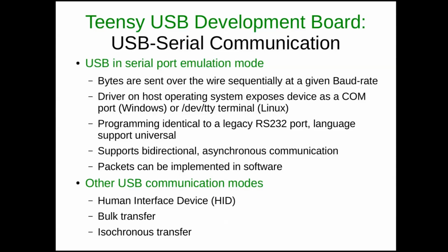We're going to be using the USB bus to communicate between our PC and our microcontroller. But it's important to talk a little bit about the different communication modes that USB uses. The mode that we're going to be using is called serial port emulation mode. This mode is an emulation of old school serial ports like RS-232 or RS-485. Those communication mediums are electrically different. They use different voltages, they communicate over different lengths of wire. Some of them use twisted wire, some of them don't. But logically they work the same way.